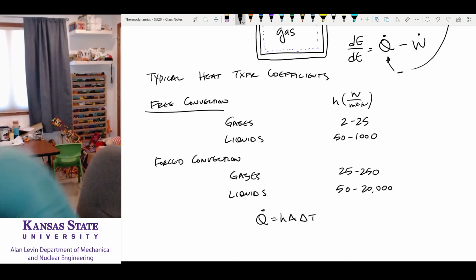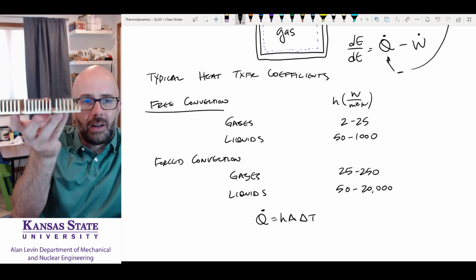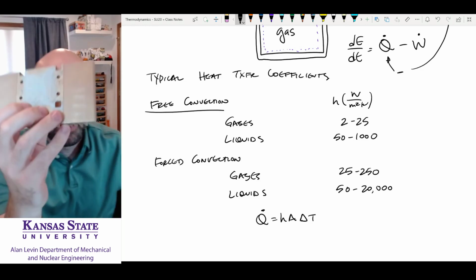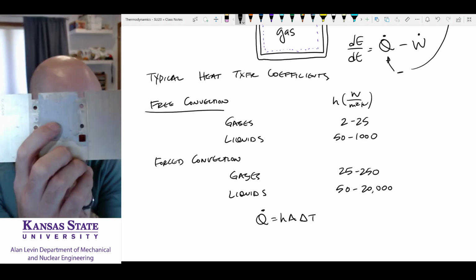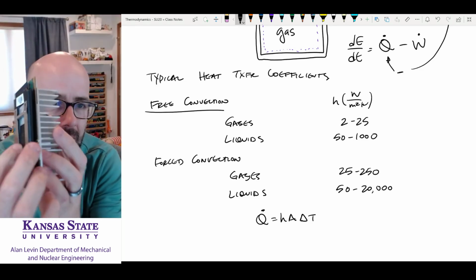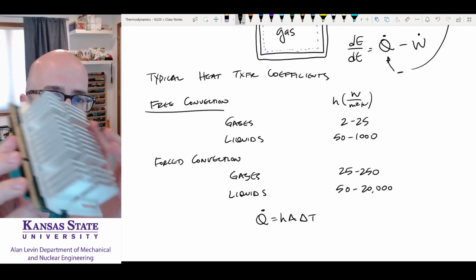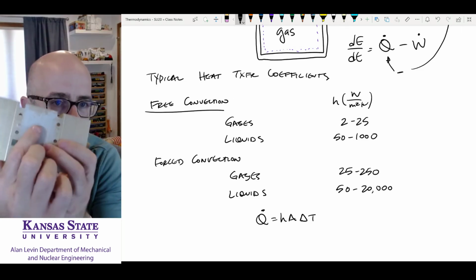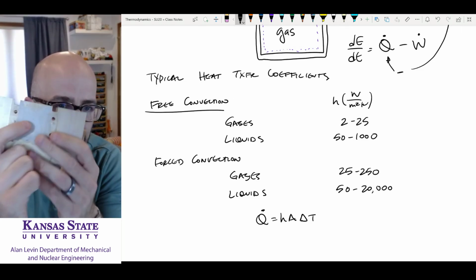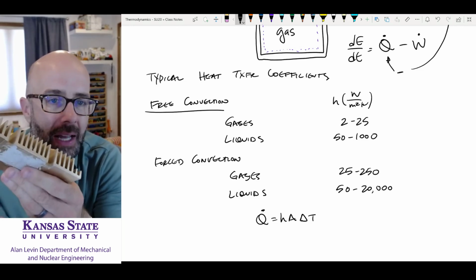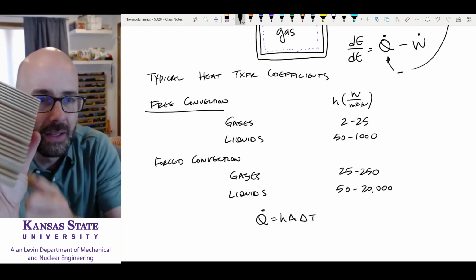Now, you may see some things. Convection, these things are in your computer. These are heat sinks. What happens here, you see on this heat sink, there is some thermal paste here, connecting it to a CPU. Here I have an old processor. It's connected to here, and I want to dissipate heat from something, and so first of all, I'm going to put thermal paste on the bottom of this heat sink, and that's going to connect it to that processor really well, and have really good conduction from that chip into this heat sink.